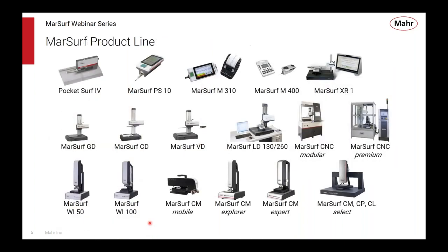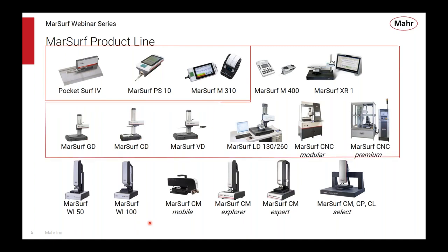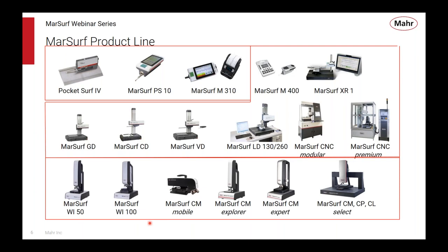The Mahr product line uses a lot of those kind of diamond stylus-based instruments, and is one of the broadest range product lines in the world for the measurement of surface finish. It's really made up of three parts, which I'm going to look at individually. There's the handheld and portable things in the upper left-hand corner. Then the middle of the screen is the stationary or skidless.